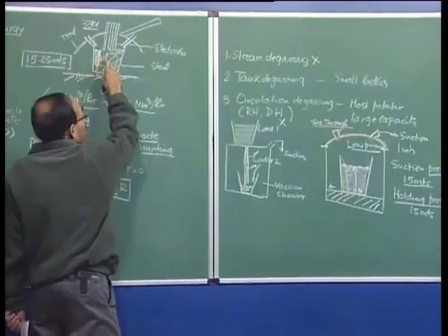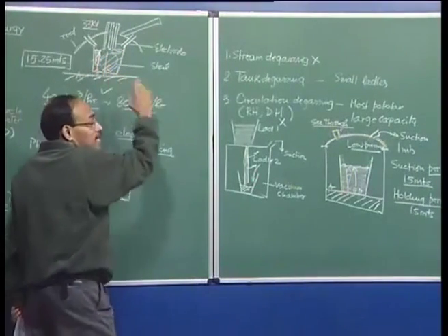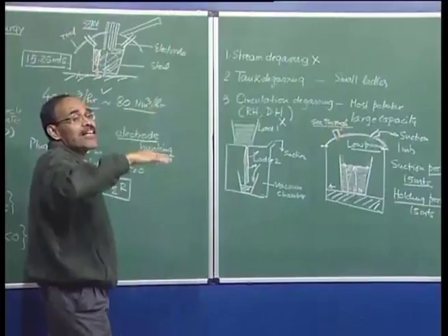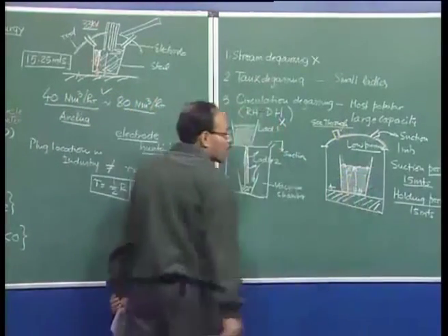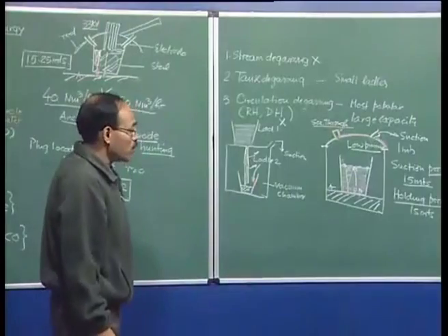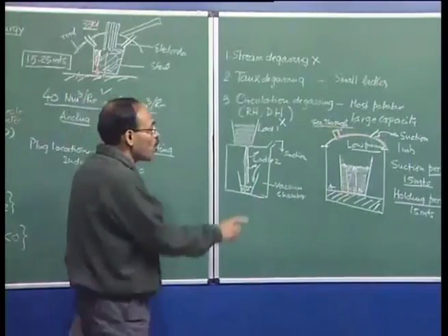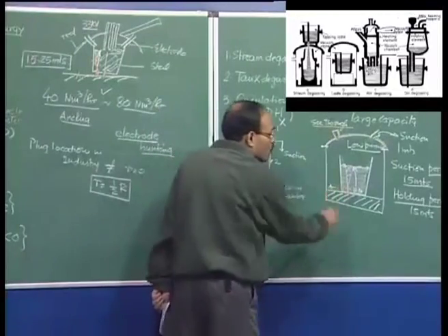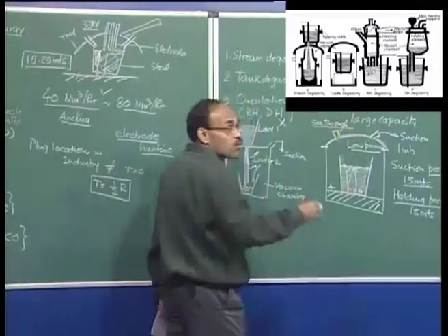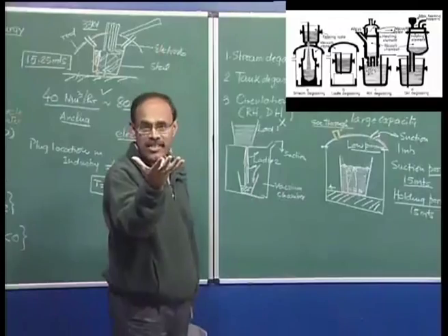So therefore the material which comes from the LF is at a higher temperature than is required by the continuous casting bay in order to compensate for the temperature drop in the vacuum process itself. We must understand here that because the pressure is extremely low, the bubbles are subjected to just the ferrostatic head, so the bubbles really grow enormously in the system.